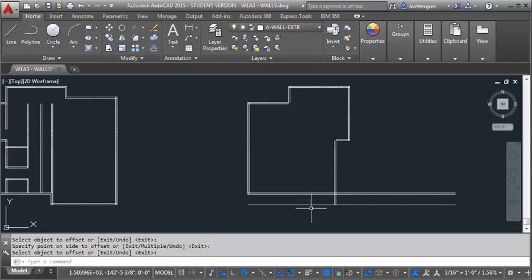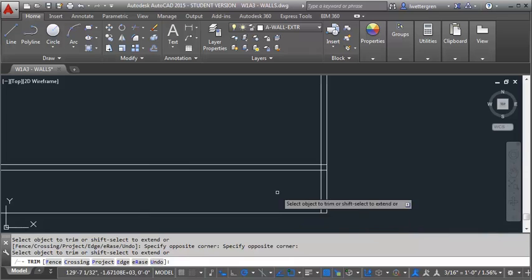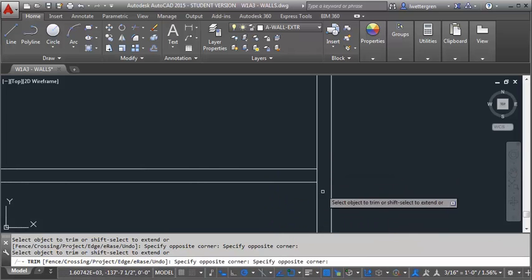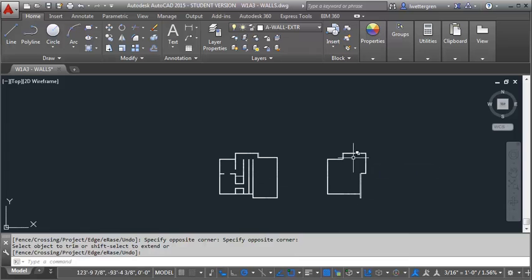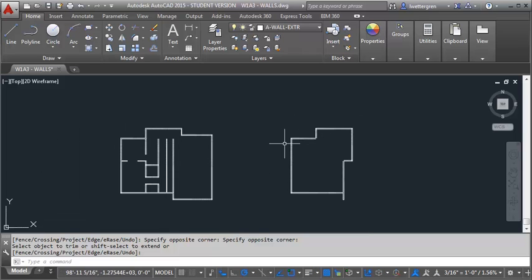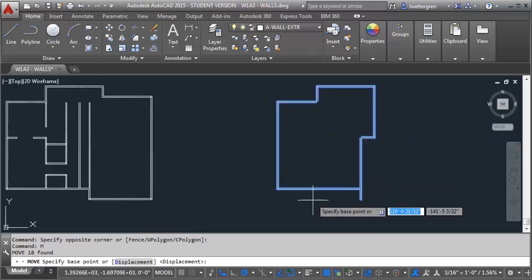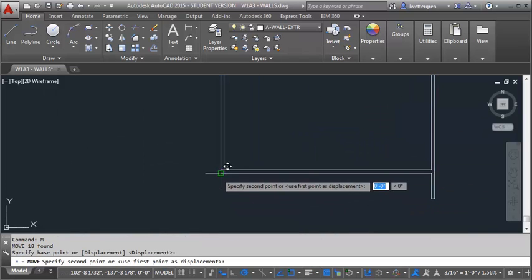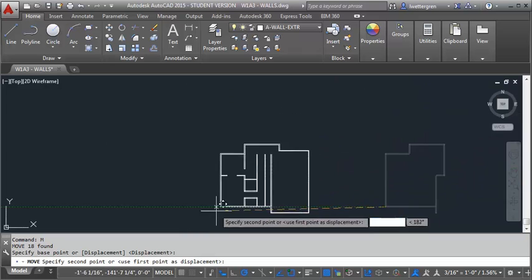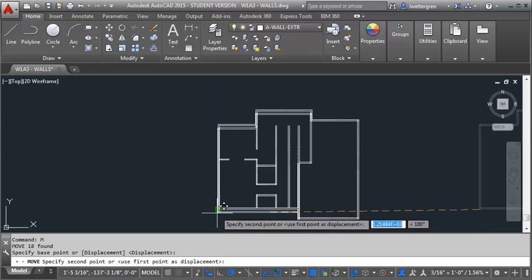And again, I'm going to go through and clean up all of my edges here, all of my corners. And then once I have all of them cleaned up, I'm then going to go in and do my interior walls just like I did on the first floor. But what I'm going to do first is take this plan here, and I just want to show you, if I move it, I pick it up by this end point and bring it over here and lay it on top of my first floor, you can see that it's lining up really nicely